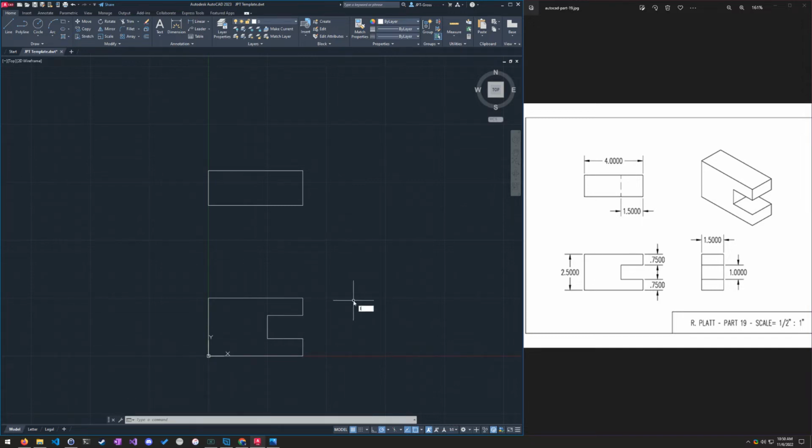I'm going to use the line tool, which is L, enter. Put my mouse here. I'm not clicking because I don't want to draw a line here, but I do want to hover my mouse up the green line until it hits the bottom of this piece. And now I'm going to click my line. That's like putting my pencil down in real life. So now I put my pencil down and now I'm dragging up, drawing with my pencil upwards.